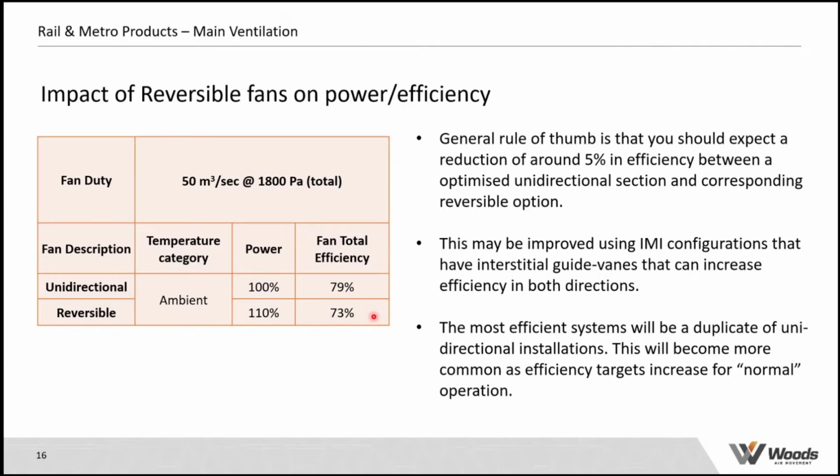And also, when you go to high temperature requirements, generally you have to have an increased tip gap between the blade and the casing, because the blades are normally made of aluminium, or even if they're made of steel, they do increase in size as they're heated, and so you have to make sure that there is sufficient tip gap. So again, the higher the temperature, the bigger the tip gap. The bigger the tip gap, it leads to a slight loss in efficiency. So we're always trying to manage the compromise between getting the best performance, but also a product that can be used in life safety.